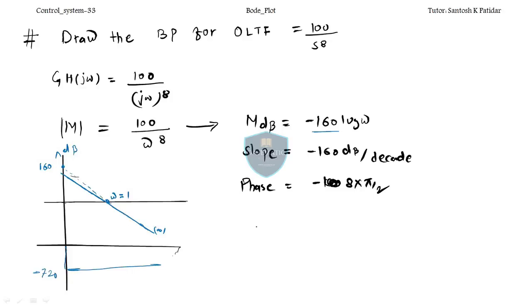Remember, in the first lecture I told you, for the Bode plot, you always shift the graph by 20 log k. This is to be done by default for any graph. In different books the approach is different, but my approach is, whatever graph I draw, after applying all these methods, I shift the magnitude by 20 log k.